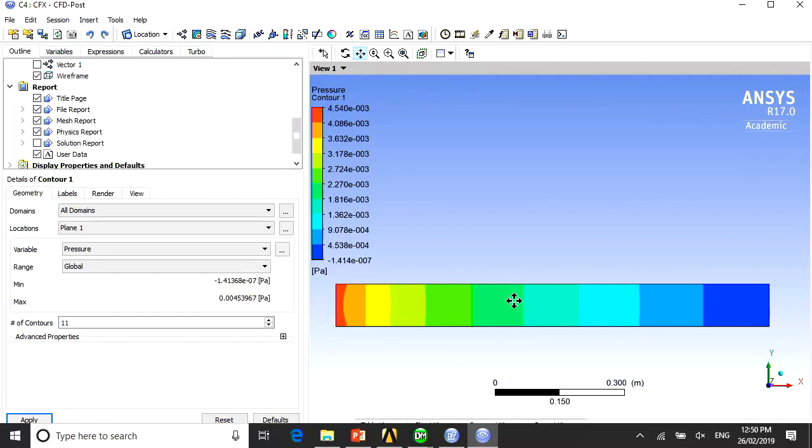Okay, it depends, it's a few things. Sometimes you may need to use double precision as one way to improve your solution. If you've got 16 digits of a value, you should get more accurate results. Second, it could be your discretization, basically the numerical approximation of your terms. Third, it could be your residual.